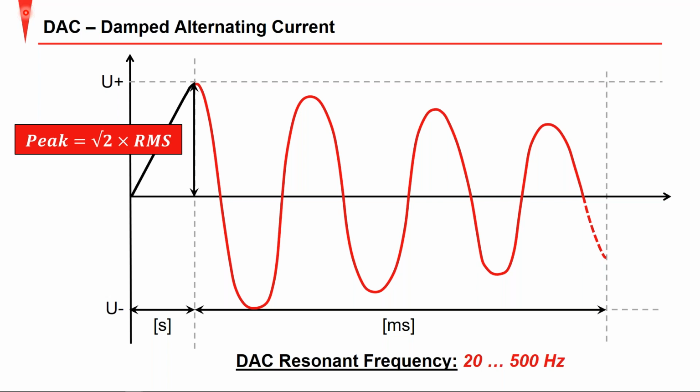So this would be ideal for performing partial discharge diagnostics on service aged cable, or a cable that you really don't want to cause stress on the insulation. Again, a very good tool for service aged cable and performing partial discharge diagnostic measurements. Plus, you are able to set your finite measurements in terms of setting your voltage and the number of excitations, and that'll make more sense when I go over the software functionality.